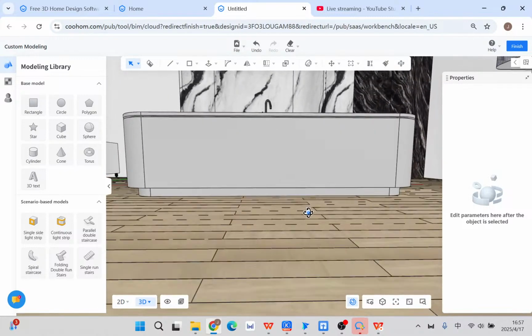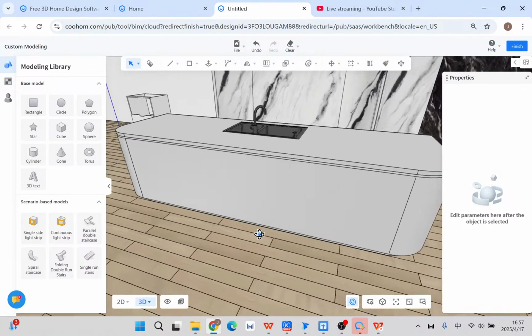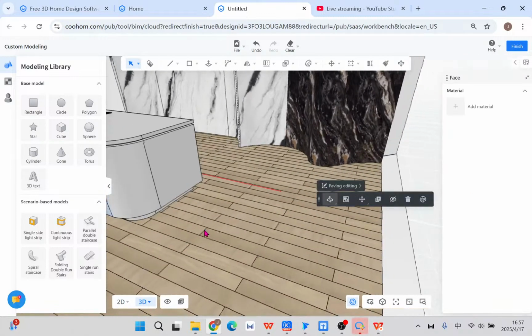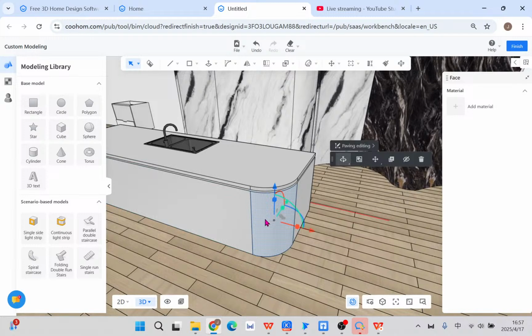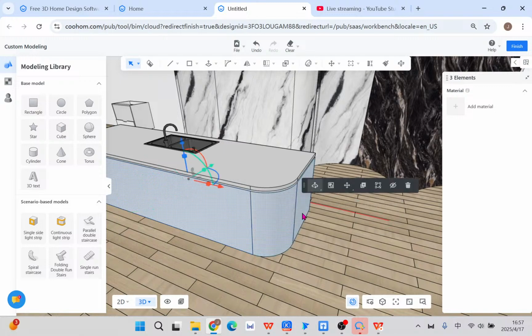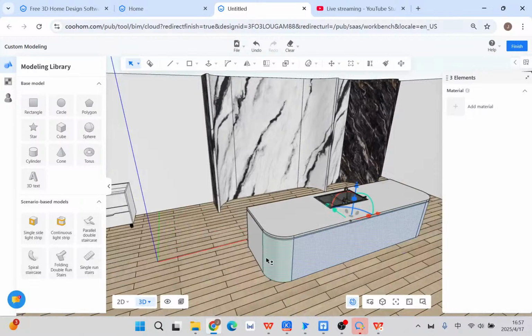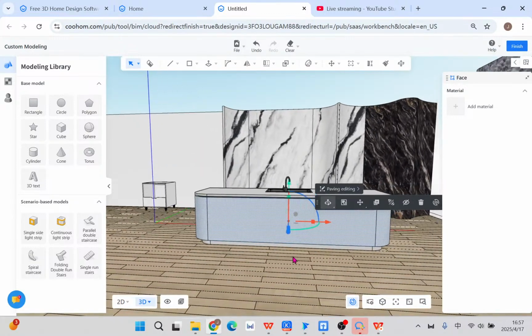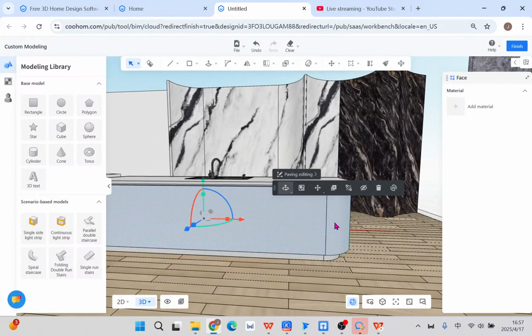Now we have just finished getting this shape, but there's still the pattern. The key thing is about the pattern and the chamfer corner. So how can we do it? Just pay attention here: holding down the shift button, select those front surfaces and you have the same connected faces. If you have ever used this function in the material component, you will have the solution.